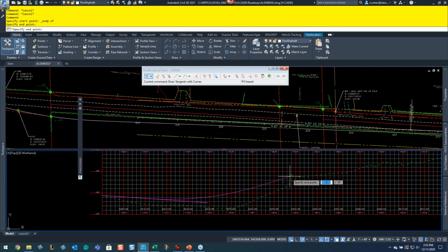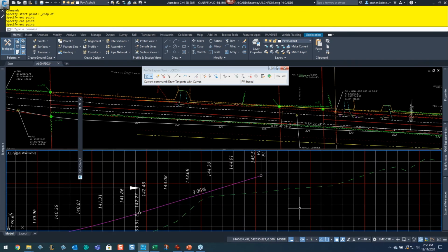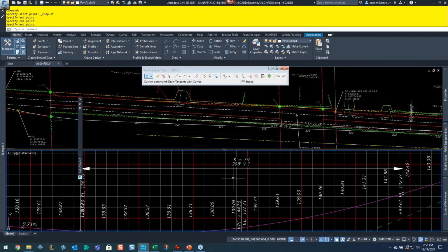I actually don't know what that is. I have not looked at this here. But obviously, as you can see, Civil 3D is doing it for me based upon that definition. So let me just press enter. All right. And so this comes up automatically, and my K value is 79. That's right. It's 45 miles an hour. And so that's being done by default.